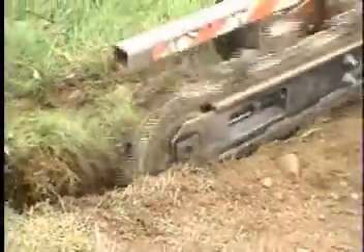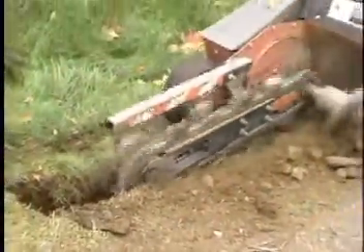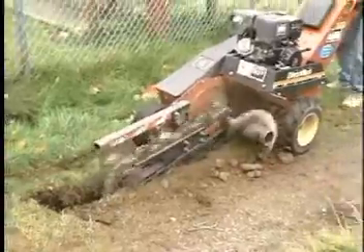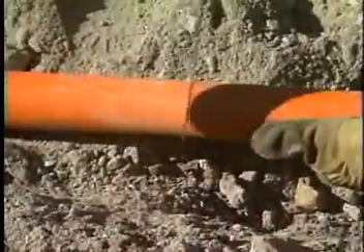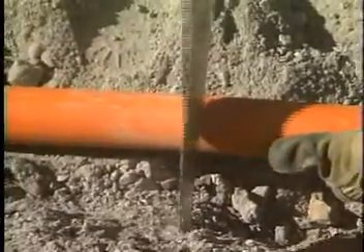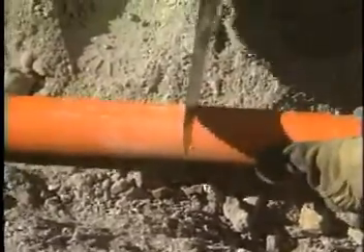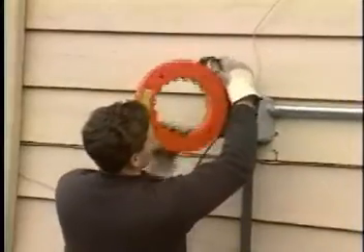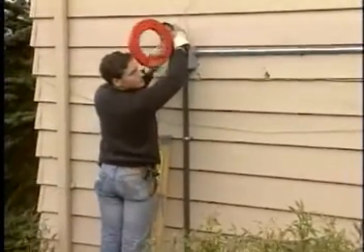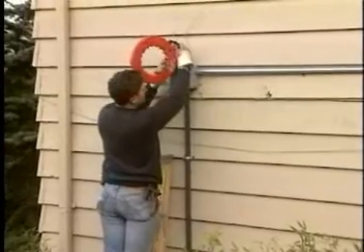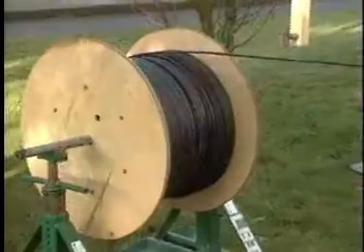A small trenching machine is used to open a trench from the building to a site near a manhole where the ducts have been exposed. The desired duct is tapped and a conduit installed in the trench to the remote building. During the installation, a pulling line is fished through each section of conduit as it is placed in the trench or blown through the completed duct.